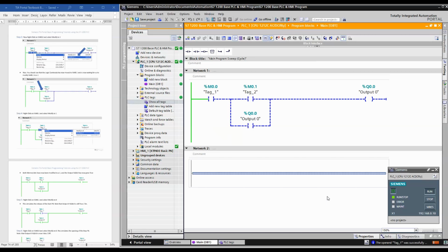All right, hopefully everything worked out for you. The next topic that I'm going to show you is we're going to replace these guys back with the physical inputs, and then I'm going to show you how a memory bit can be made use of to turn on different portions of our program. So right now I have a physical output that's turning on, but we're going to change this to %M0.0 for an output, and then have that turn on different portions of our program.